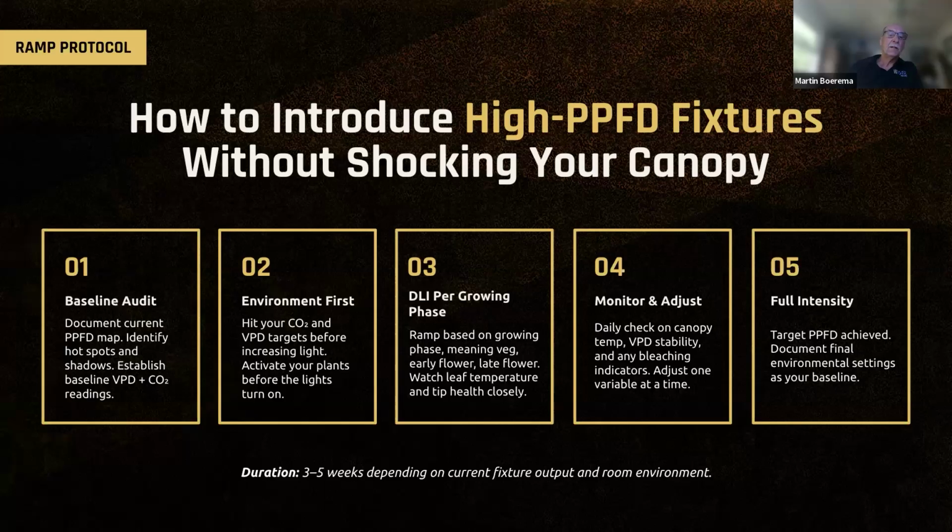Make sure that your sensors are accurate. What I see a lot of times is that if sensors are not accurate or not calibrated properly, you base your decisions on faulty data, faulty information. So make sure that everything is kosher to start with. In the greenhouse when I was a grower, I was calibrating my RH sensor all the time, because otherwise my windows would open and close at the wrong time. So make sure, once you start your grow, to trust but verify everything that you have set.